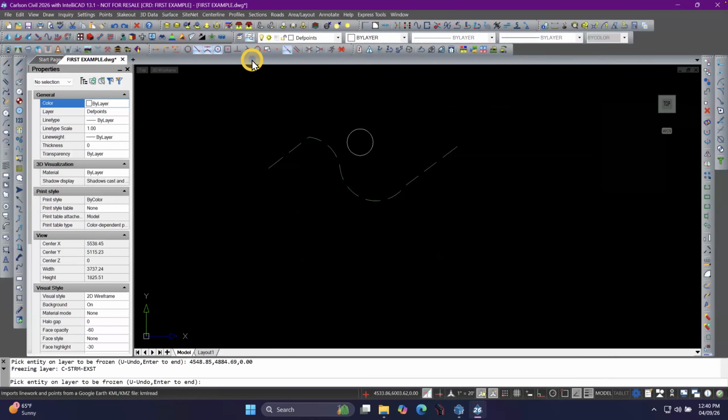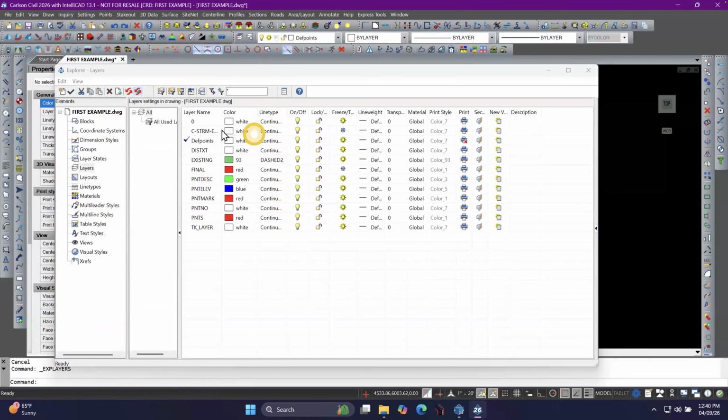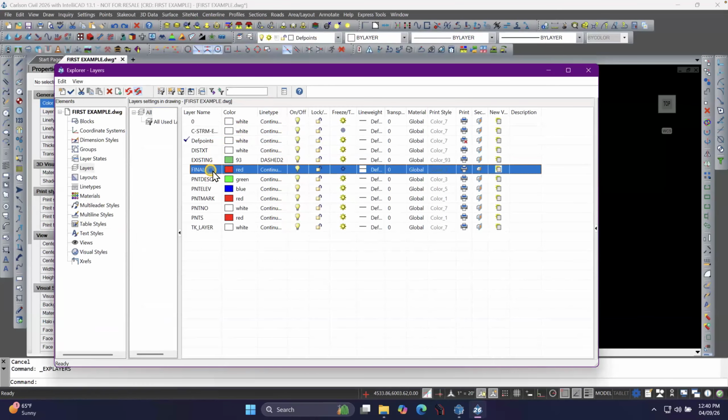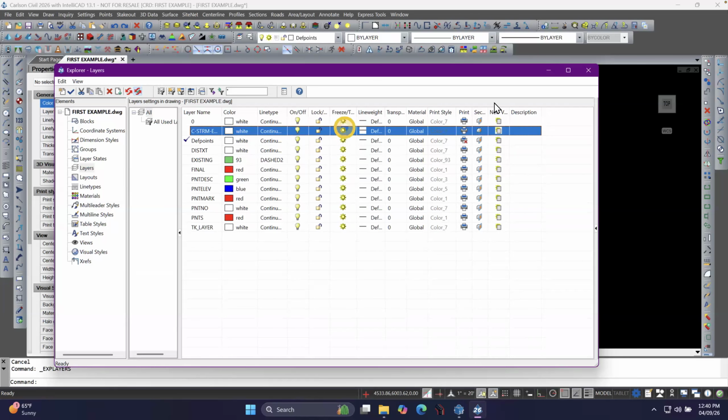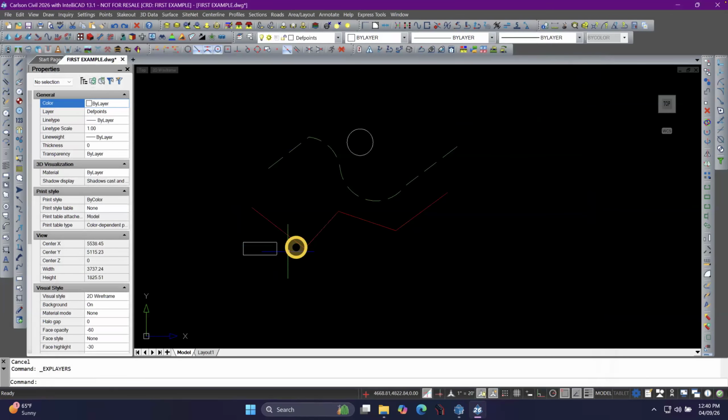So that's the same effect as if I had gone in here and selected this layer and that layer and chose that little snowflake instead of the sunball. You can turn them back on, you see, and they'll set back. So any of those ways are ways to help you isolate different things, to just work on a couple of things, and you don't want all the other mess in your way. Just isolate them and keep them separate.